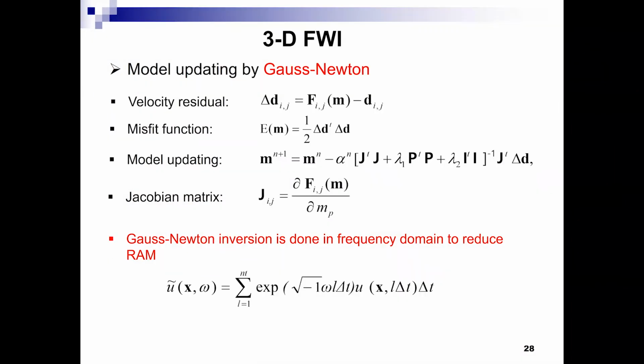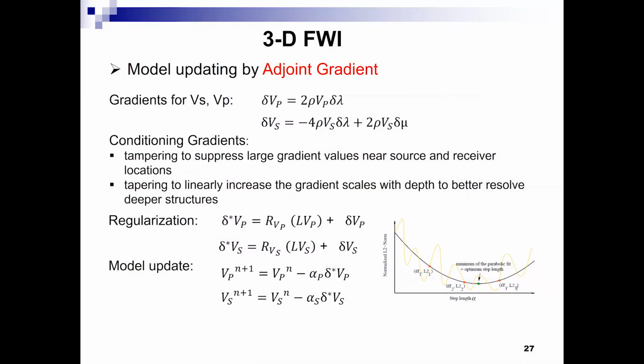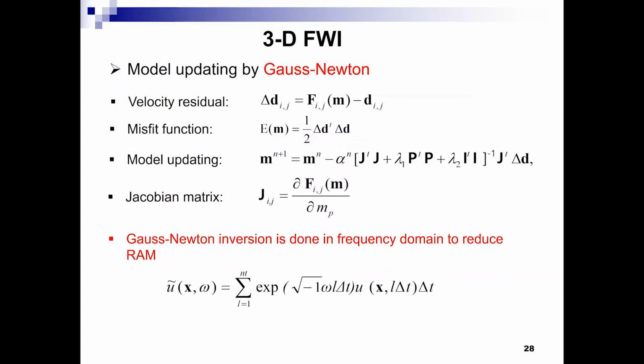This method works very well for layers. Soil and rock layers are identified well. It's not so good for voids. For the void, we couldn't see it very clearly because of the near-surface artifact. So that's why we had to come up with Gauss-Newton again.